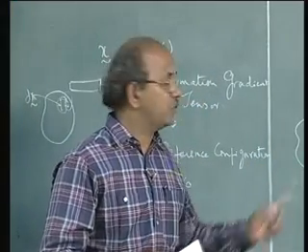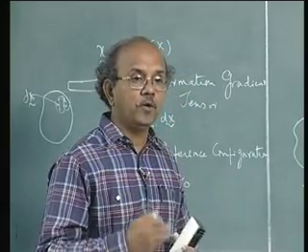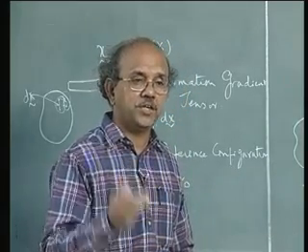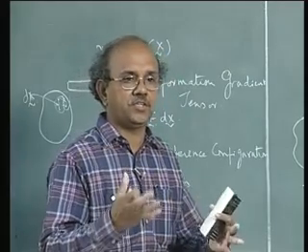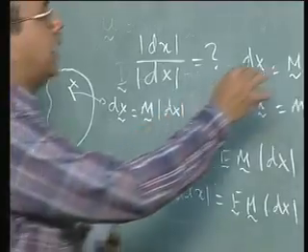So in this case we are taking a material line element, and the orientation of the material line element may change, and accordingly each stretch would also change, and that's the reason why we have M here.